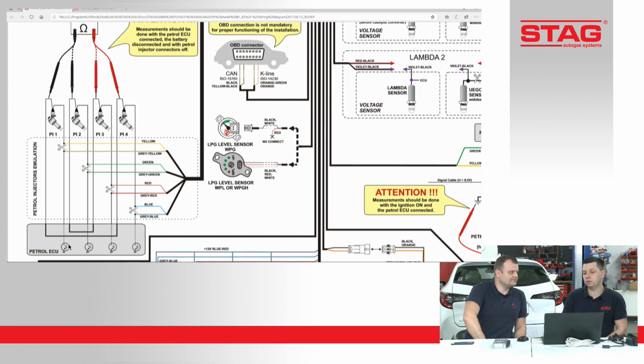If you switch the cables, if you connect the cable without a stripe, the solid cable, to the ECU, and the gray-yellow in this example to the petrol injector, the system will not work properly. Sometimes, in some engines, if you mix all 4 wires, the problem will be that petrol will not be cut when the system switches on the gas. There will be no side effect except that both fuels will be used at the same time, if you switch all 4 wires.